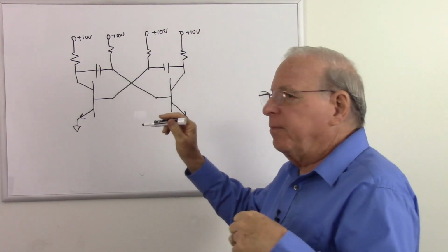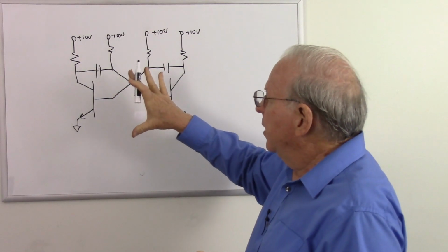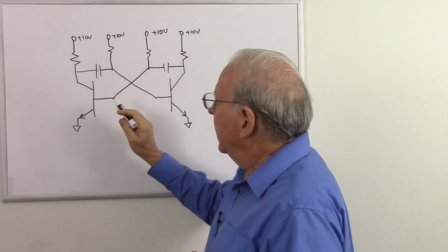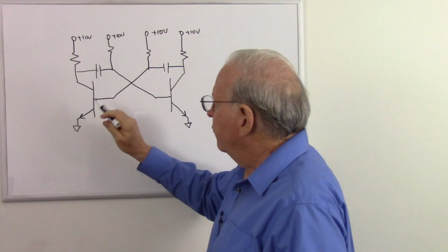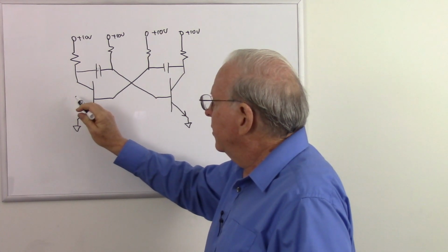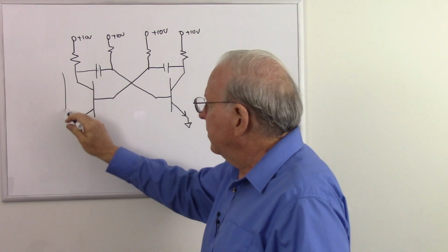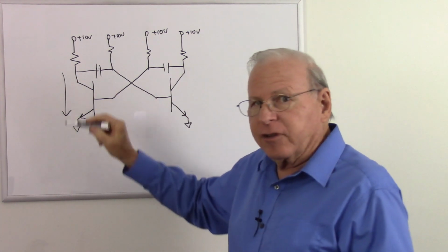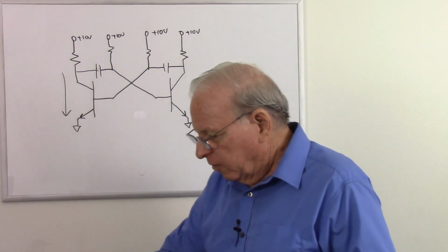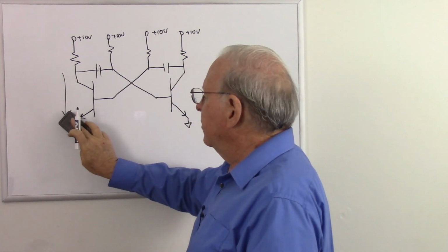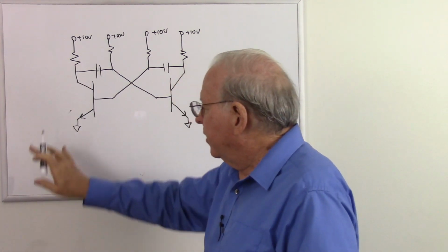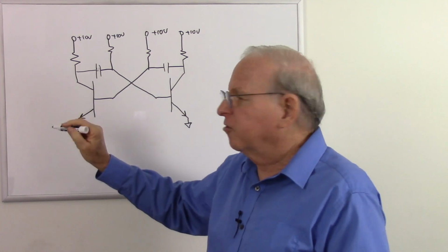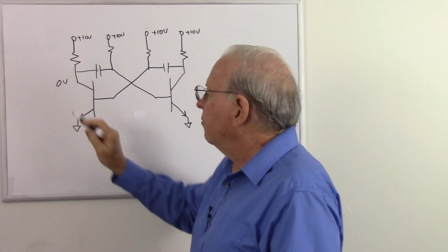And it's going to very quickly put us into the situation I'm going to put us at right now, which, let's just say at this point this transistor is turned on. So we have a large amount of current flowing through there. It's basically a closed switch. So if we have a closed switch, how much voltage difference is there going to be between here and here? Well, if it's a closed switch, it's a short circuit, we're going to have 0 volts.